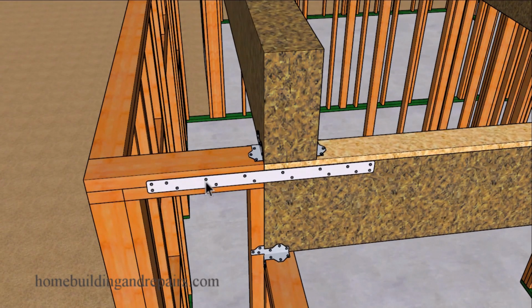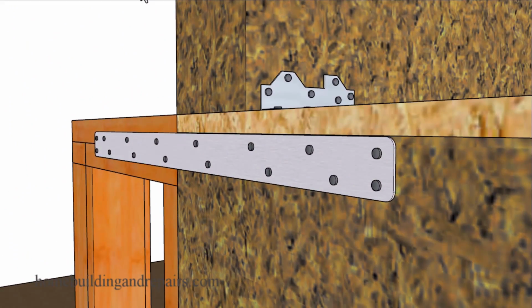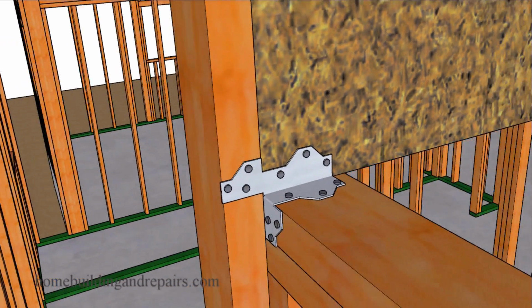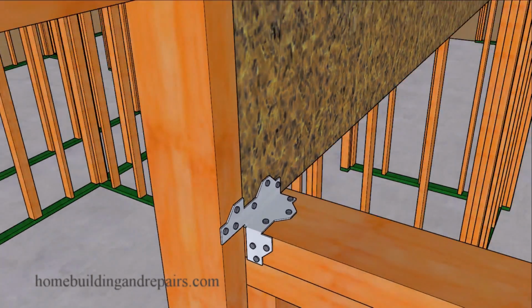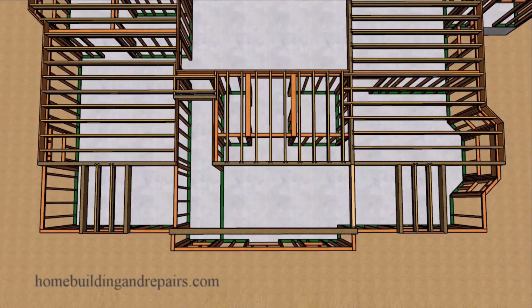And we're going to use another strap to connect the wall framing to the beam, along with some building hardware to connect the beams to the wall framing or even the other beams. And you can always use stronger connectors, and an engineer might actually call out for different connectors. Keep that in mind. And this beam will help tie this wall together so that we get a nicer connection between the sides here.